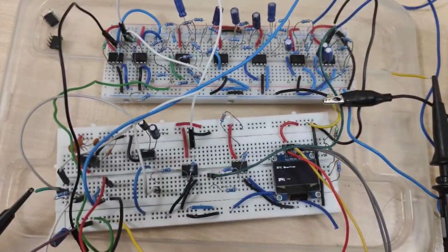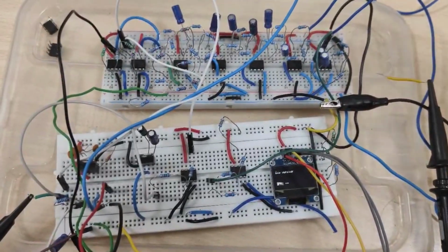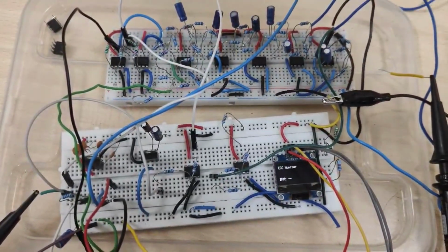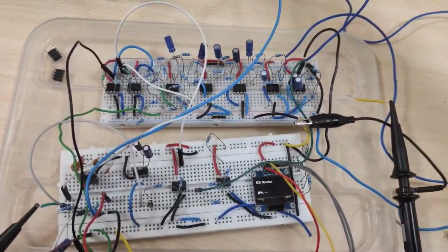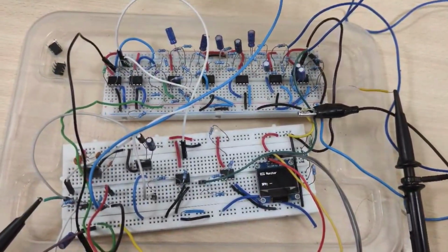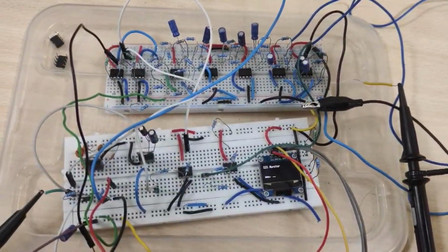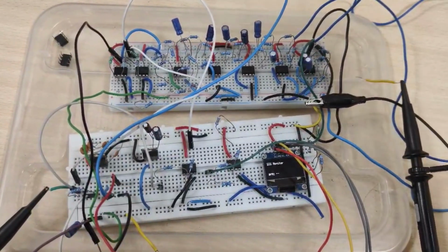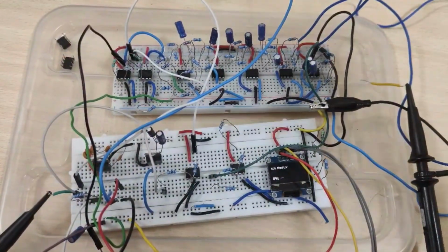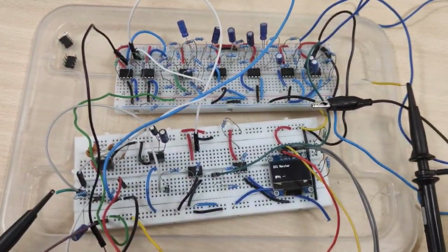A low-pass filtering stage is designed to attenuate high-frequency noise and stabilize the baseline of the ECG signal. It uses a cascade of three second order Butterworth filters, resulting in a 6th order filter with a sharp cutoff of 35 Hz. This cutoff frequency is chosen to retain the primary frequency of interest in the ECG signal, while effectively filtering out the power line interference, which is at 50 Hz, and the other high frequency noises which we do not want.